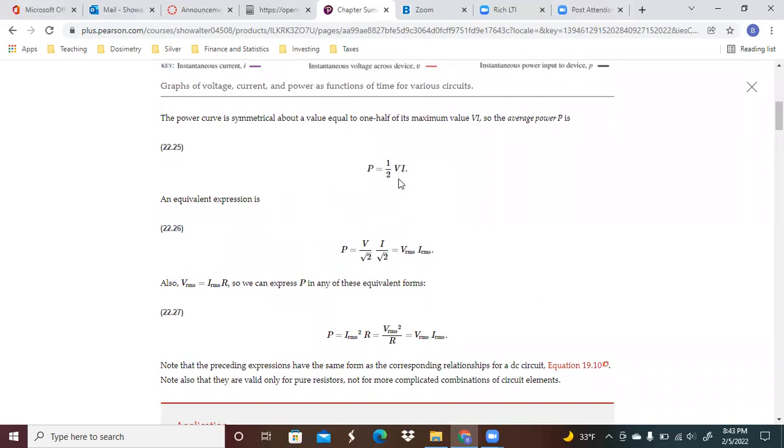Here again, this is the relationship of the amplitude of the power and the voltage and the current. You can see the same thing over here. You've got V of RMS, I of RMS, and that product here. You can see where the square roots are taken care of, or involved, because we're dealing with the root mean square, and that basically gets rid of the 1/2 here.